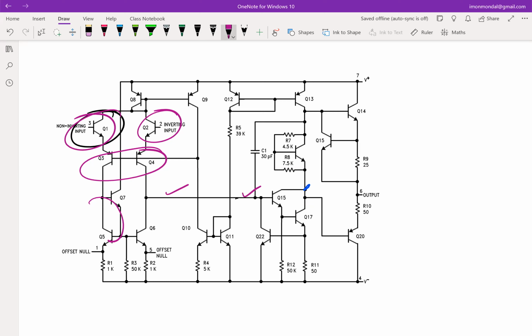So this increases, and similarly, this becomes your output, right? So you assume that this is shorted. That is done for level shifting purposes, just to have a difference in voltages between these two nodes. You can assume it to be shorted. So the second stage, your Q17, gives you the second stage. This is the second stage incremental current. Q13 gives you the active load.